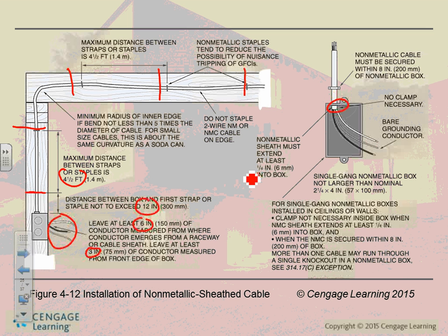No clamps: you have to allow 1/4 inch of the insulation. Can you see that right here? And for all of them. And if you don't have clamps, you have to staple within how many inches? 8 inches versus what? 12. That's all. No problem. Just staple them 2 inches less. 8 inches. That's basically it, guys.